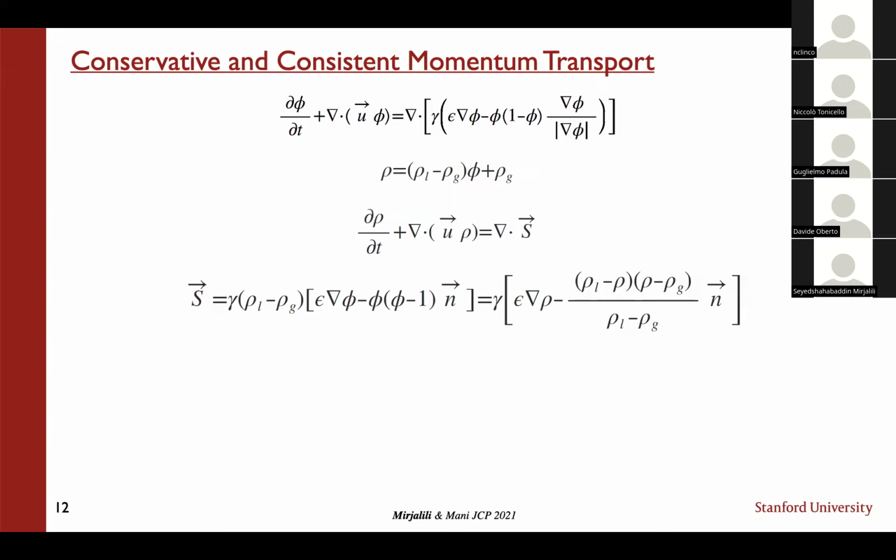Let me go one by one. This is a staggered grid configuration, and the kinetic energy is conserved even though we have a conservative implementation for the advective term. Even without the skew-symmetric form, you can show that the kinetic energy is conserved.